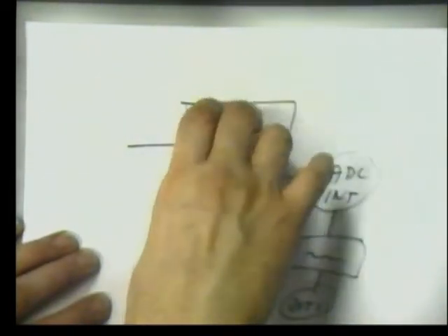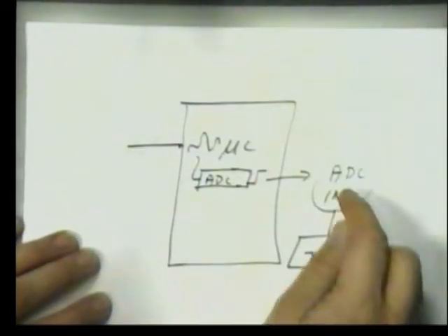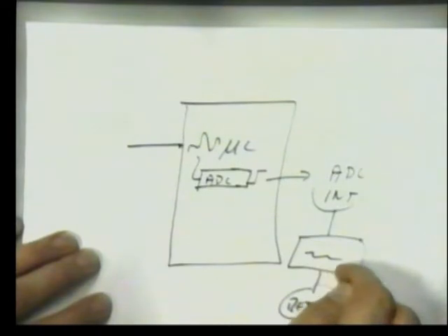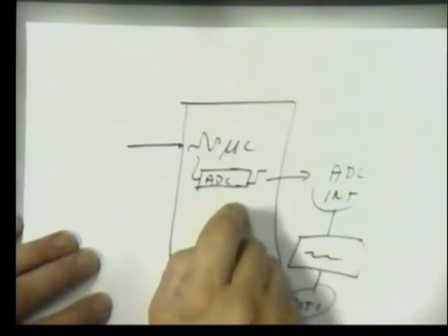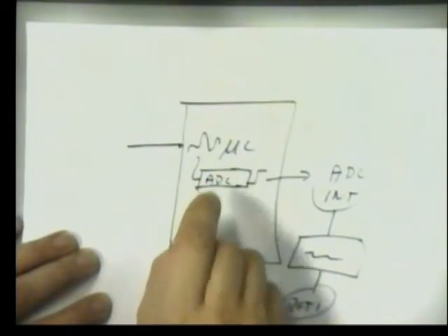And the example here is the ADC. You now have that integrated into the computer itself, so that the ADC interrupt tells us the ADC routine, the ADC has completed its job, and it's all memory mapped. So we can go straight to the registers. The ADC, not only does it do the conversion, it drops the results into little boxes for us in the memory of the processor.